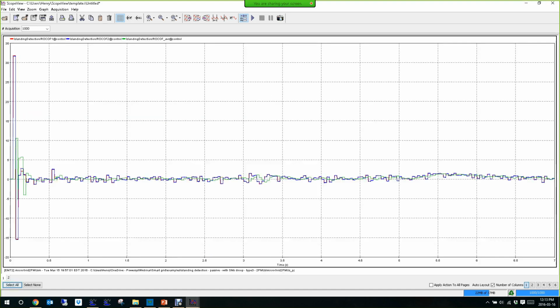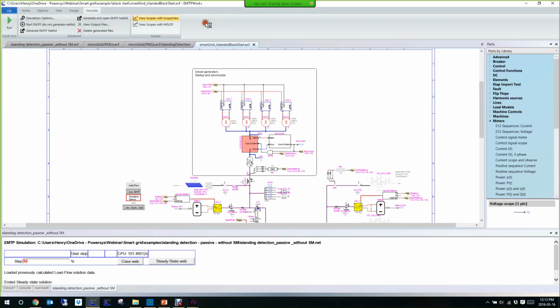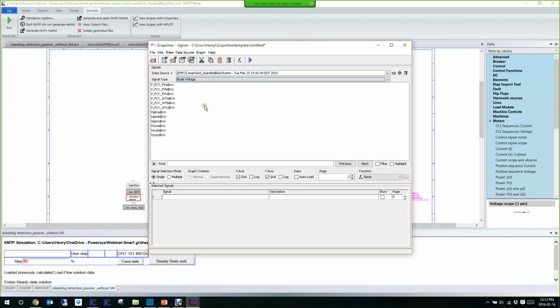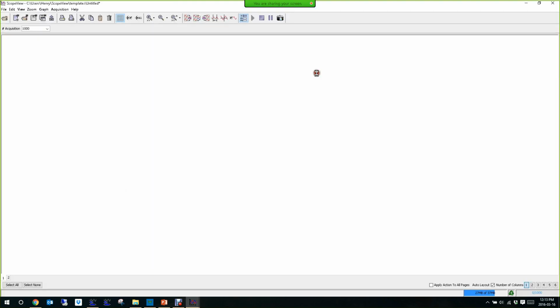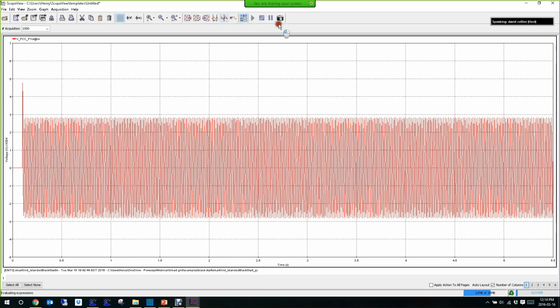Okay, so let me remove the plot before and look at the result. So I click on View. I ran this simulation already because, again, we have no time. So first let's start with the voltage at the terminal of the battery. So if I go to the node voltage, it's here. Let's only look at the voltage on phase A. Initially, nothing. We are at 0, then we start, and then we are energized.